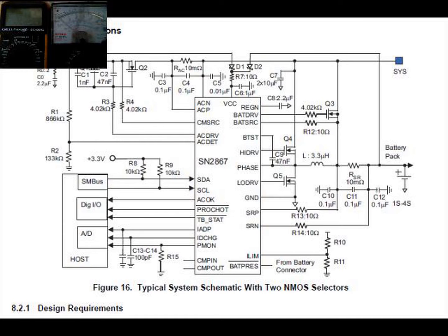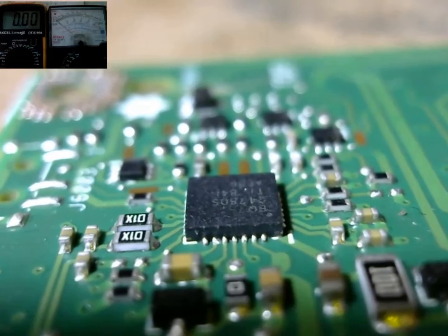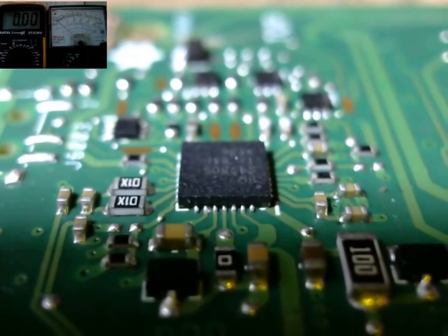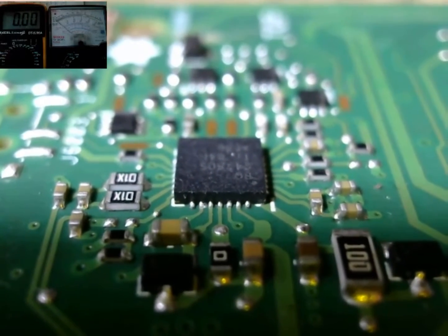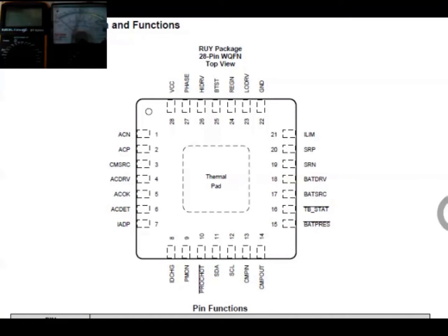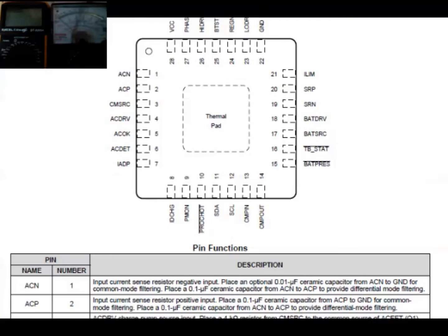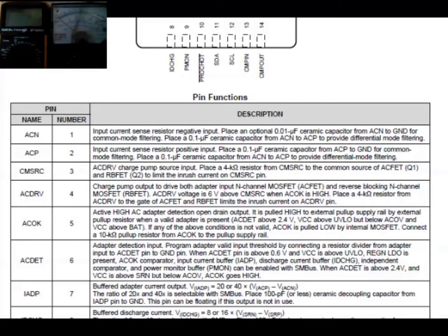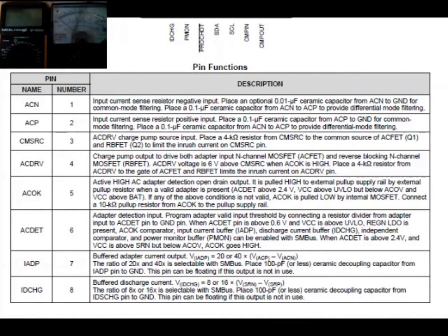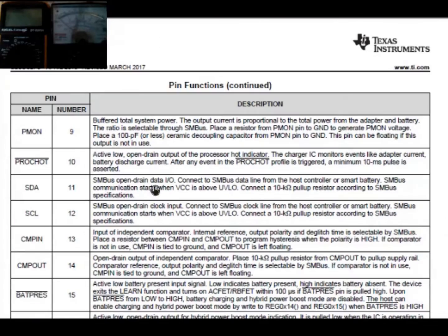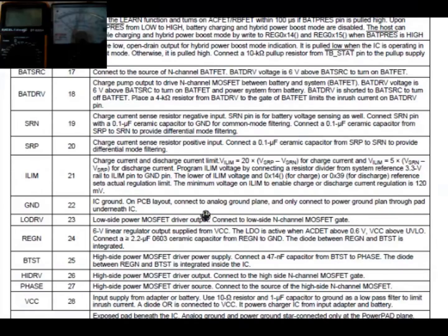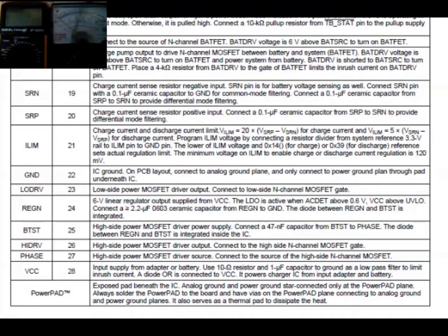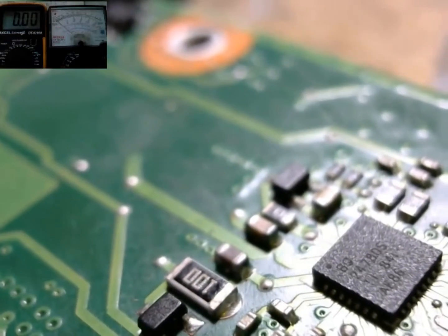We will know how, for example, of this problem, because the problem is about the charging process and is usually caused by something wrong at the block of the charging system that controls the charging, with an IC called the charger IC.